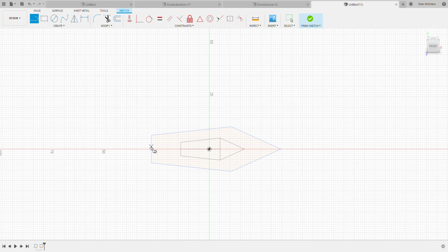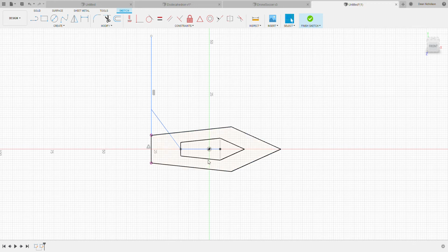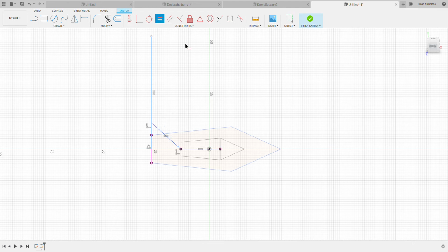You want to take a line, draw it from this guy all the way up, just wherever. Just make sure it has a decent amount of height. Kill that. And then you want to do a line between here and there. And then you want to move to this sketch the line that exists from there to there in the other sketch. So in order to get this line and its width right here to occur at that point, you select that line, shift and select that line, and make those two equal.